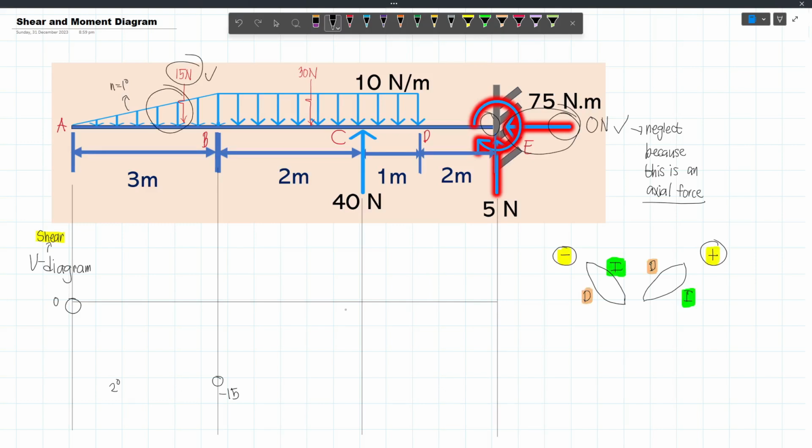Now, looking at our figure, we have a triangular load which acts downward. And if that acts downward, then that means that we are considering a negative load. And so, we will be considering this leaf because it is negative. And then next, we will consider the magnitude. Our load starts from 0 and then ends at a certain value, which is this 10 newton per meter. And so, it's essentially increasing. So, we will consider negative and then increasing. So, we will be considering this curve or simply this one. This curve, because again, this load is negative increasing.